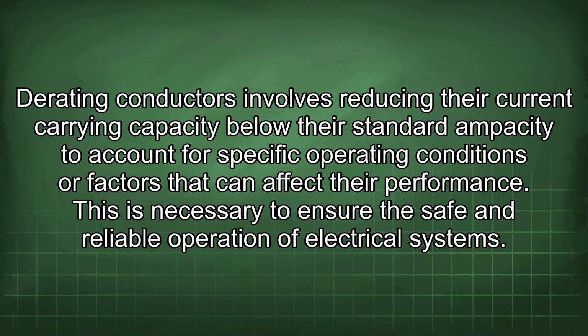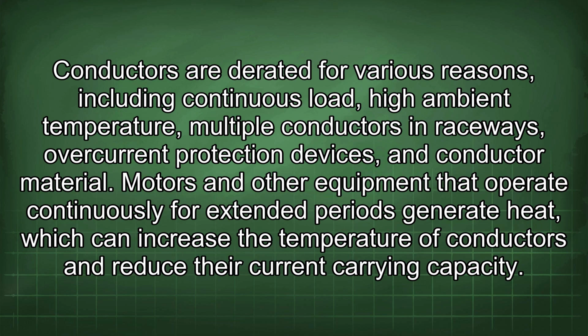Derating conductors involves reducing the current carrying capacity below their standard ampacity to account for specific operating conditions or factors that can affect their performance. This is necessary to ensure the safe and reliable operation of electrical systems. Conductors are derated for various reasons, including continuous load, high ambient temperature, multiple conductors in raceways, overcurrent protection devices, and